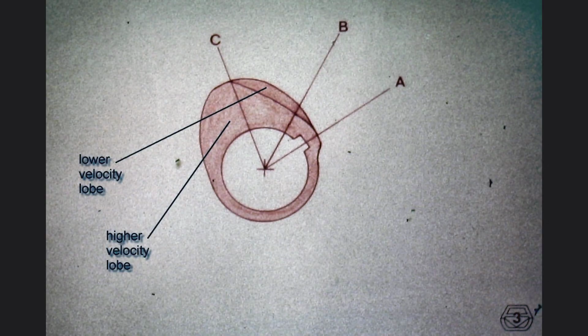From this, we conclude that the cam follower has to move at a greater velocity when it has to move out of the way of the right cam lobe. The same is true of the rocker. It, too, has to swing toward the platen at a higher speed when the lobe on the right of the cam, in the foreground, causes it to move. As a result, the lobe in the background on the left side of the cam is called the low-velocity lobe, while the lobe on the right is called the high-velocity lobe.